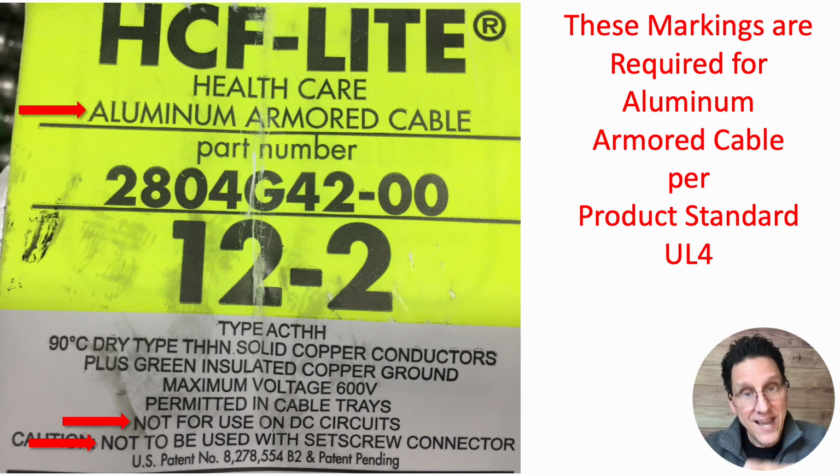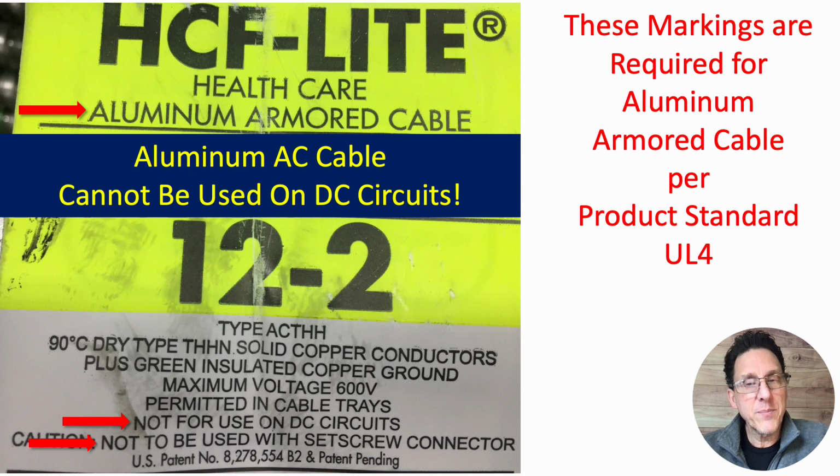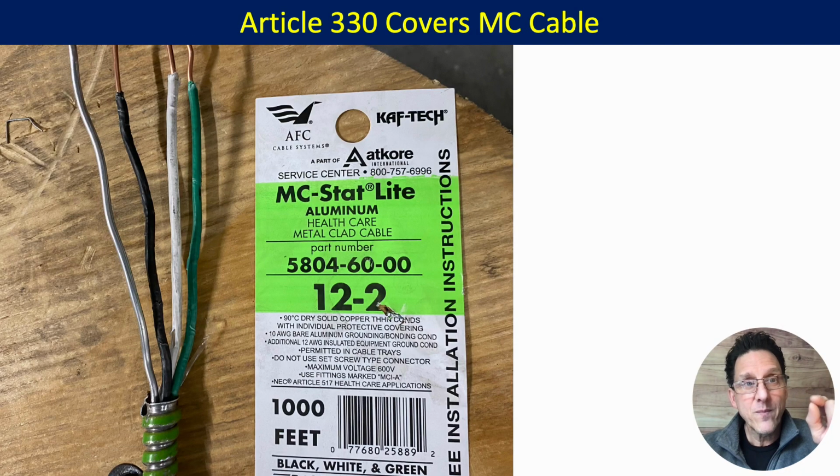Well, on the inside of the cable itself, there's a ribbon. All right, so aluminum AC cable cannot be used on DC circuits. Even on the inside of the cable, there's a little ribbon that says not for use with DC circuits. Interesting, right? Now, what's even more interesting is this. Aluminum MC cable, perfectly fine for DC circuits.